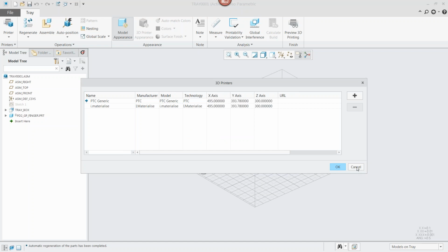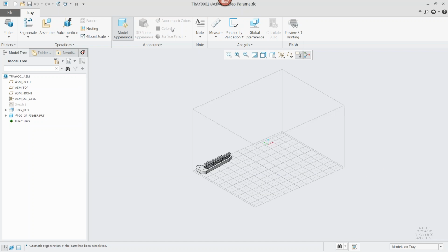Stratasys and some 3D Systems printers, you can print directly from Creo. And you even can change the appearance. You can choose what color you want. You can calculate the build all within your software. So if you are designing a piece, a plastic piece, I just want to see how long it takes to build. You find out it takes 48 hours. Okay, I need to go through and make a change. Oh, right here, it's building a lot of support material. Maybe I can work that down a little bit to cut this out.